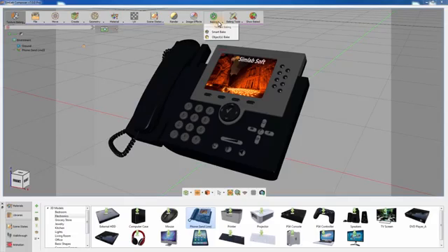The second tool is Object Baking, which is similar to the traditional baking and will produce texture maps according to the face normals of the object. From the Baking Tools menu, you can clean the model of any baked textures. You can also break the objects to faces or to geometries and merge them according to their materials, which are helpful tools that optimize the model prior to the baking process.